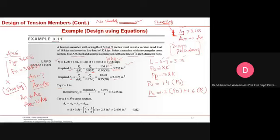You can assume any thickness, then you can calculate the width of this member, because the gross area we already know. Once you divide the gross area by the thickness, you will get the width. So you will say that let's assume a cross section having these rectangular dimensions, 1 into, now this is the thickness and this is the width. So you can try this member.